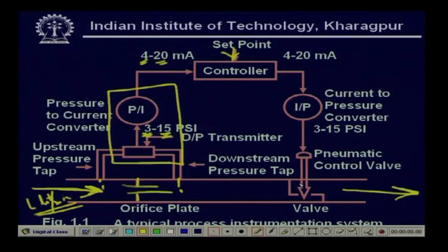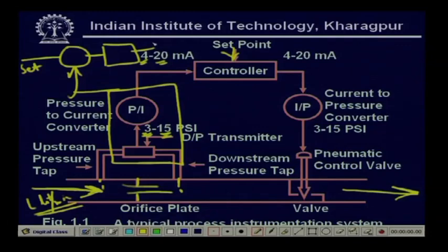So, where will I get that signal? I will subtract this signal from the set point. I have a set point, I have a signal, so these two signals will be subtracted. When we study control systems in future, we will find all those things in detail. That means I have a system here, this is our set point and this is our error. So, this will be kept and this will come to the controller. I have a process, it will take actions.